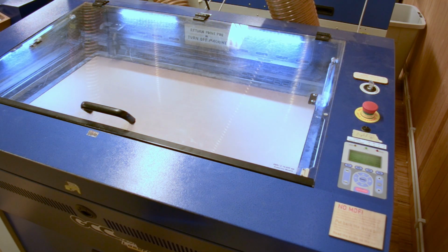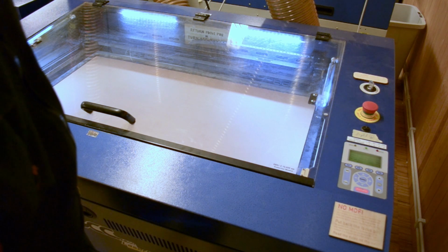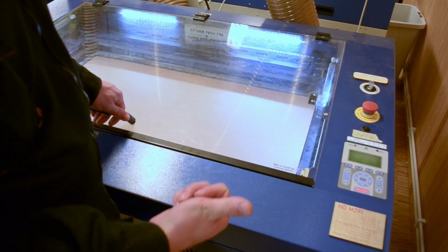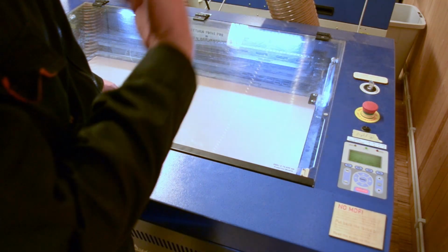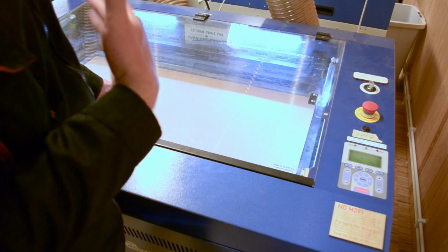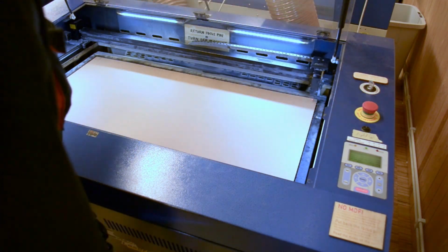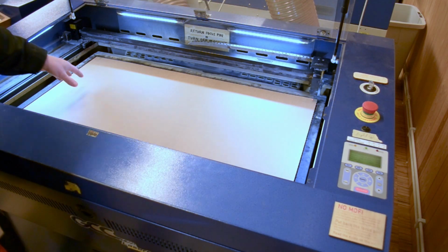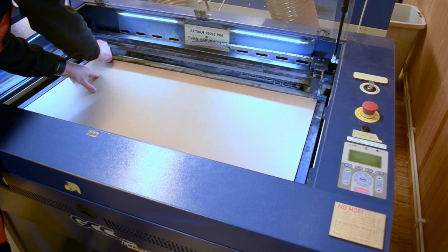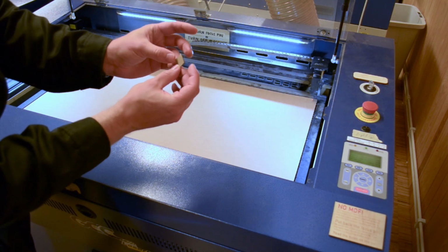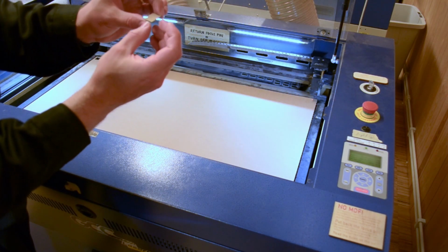Doing a test run like this is recommended because in 5 to 8 seconds of active laser cutting time, it gives you a fairly clear view whether the settings you have chosen are adequate or not, so that you can revise this in a succeeding test before finding the adequate settings with regards to speed and power, so that you can start your final projects knowing that the settings are in the ballpark of being correct.